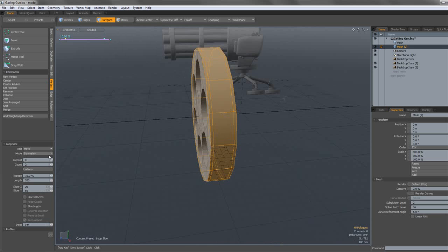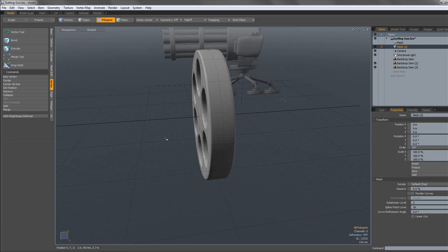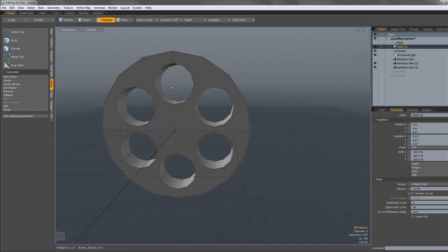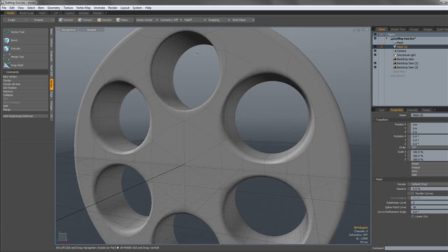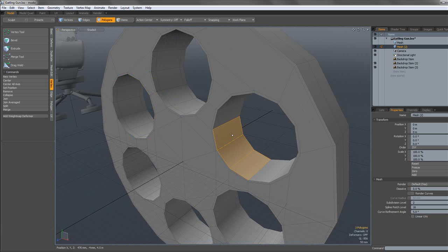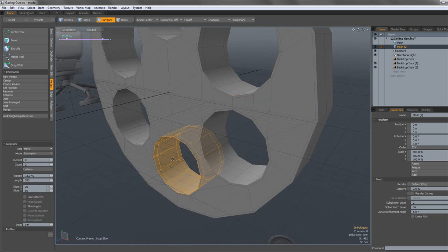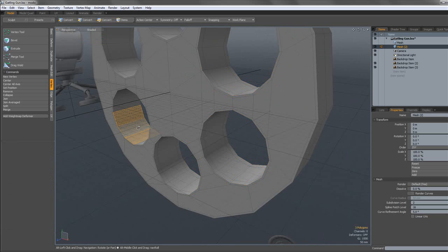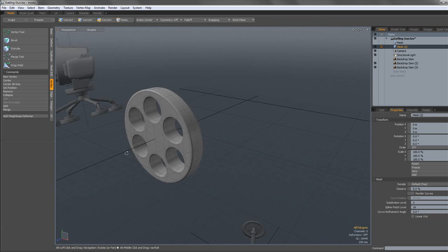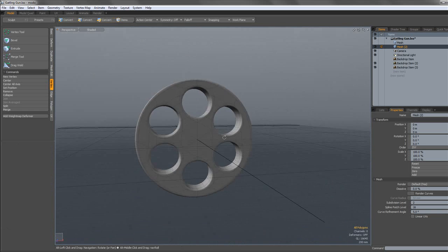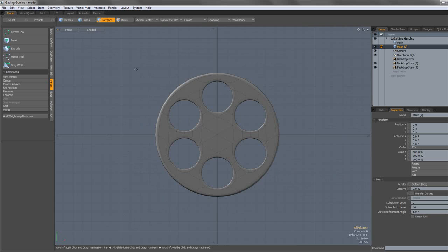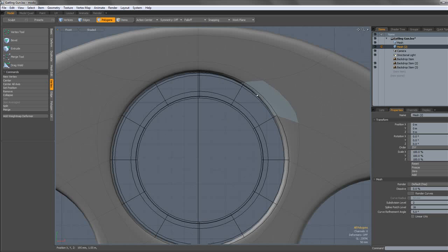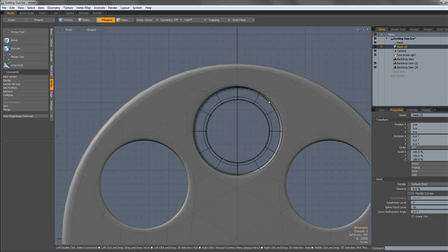and we can probably afford a single edge here just to ease the smoothing process. Okay, and we can add 2 support edges on the inside. Okay, I'm just repeating the process, selecting polygons and then using Alt-C. Okay, and there we have it. This is our support. And let's go to the front. Now you can see that the barrel matches.